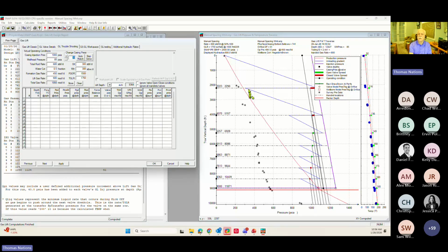And then it's not going to use the transfer pressures as the tubing pressures. It will use the actual flowing tubing pressure off of our objective liquid gradient curve. It's going to recalculate all the surface closing pressures, and it will calculate the gas throughput volumes for all the gas lift valves using whatever model we chose. The one that's going to be accurate here, calculating against the 600, is going to be the Winkler one.